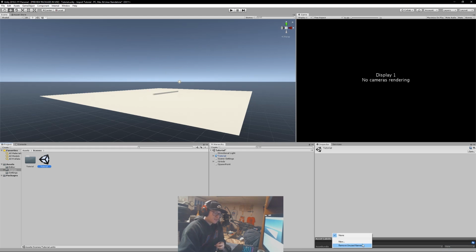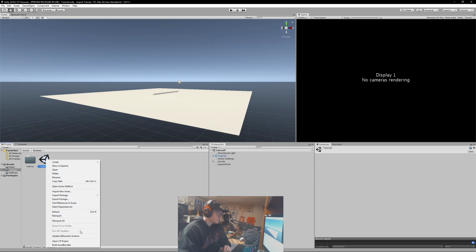So what you do is you just click on it and you can click new, and it's going to ask you for a name. Again, I'm just going to call this tutorial park. And that's it. Hit enter, and you've now created your asset bundle. So now how do we get the actual map? Click on our scene over here, and you remember that script we created earlier? You're going to right click on tutorial, and you just click build asset bundles. So let's click that.